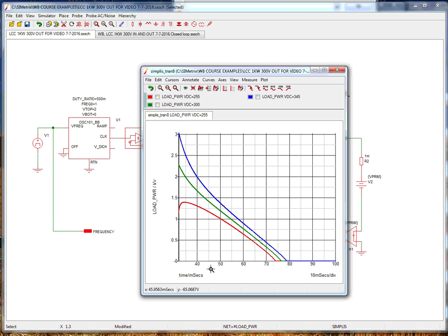You see three curves. Look at these numbers in the x-axis. They actually stand for 40 kilohertz, 50 kilohertz, 60 kilohertz, 70 kilohertz, 80 kilohertz. Now remember that we wanted to design so we got 1 kilowatt at 50 kilohertz. This is the low line power curve. You see it peaking right here, well below where we're going to operate, which is about in here and here.